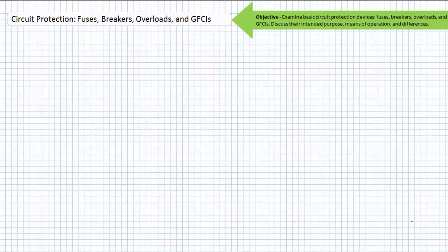The metal innards of the fuse are sometimes packaged in glass cartridges or plastic blades for automotive applications. These transparent cases make inspection of the fuse incredibly easy. You just look at it. If the metal strip inside is melted, the fuse is blown. If the metal strip inside is intact, the fuse is most likely good.